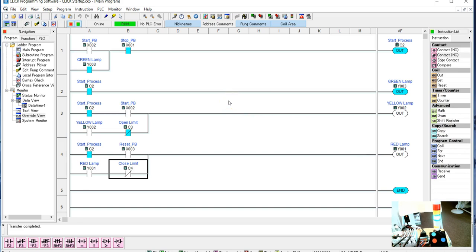And you can do a lot, and you can also do a lot just with using this stack light. You can kind of make up different scenarios, and you can have different functionality with some of these bits. You can also, and this is really powerful, use this override view to put in something that we have no control over, like this C3 or C4, except by using this override, and we can actually force it into some condition that'll show that our program is working, and that's a valuable tool.